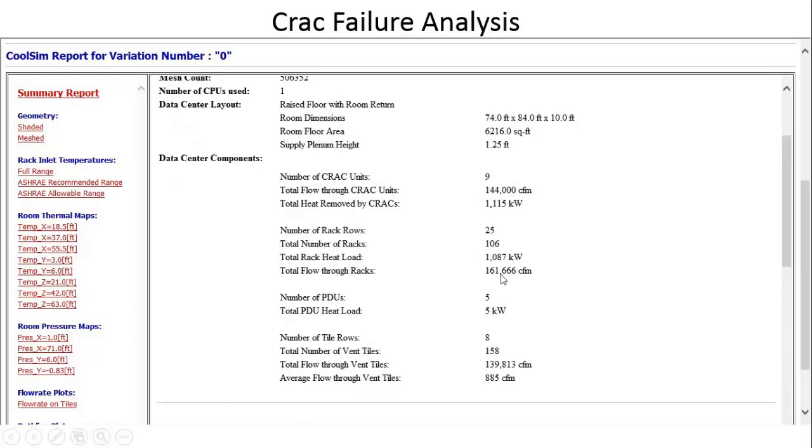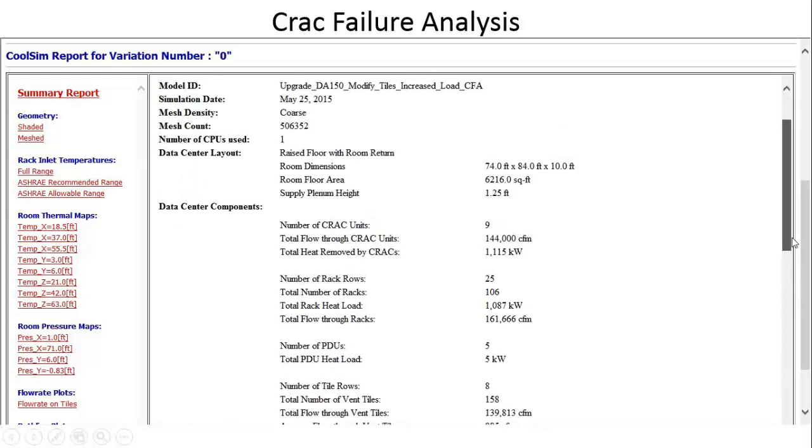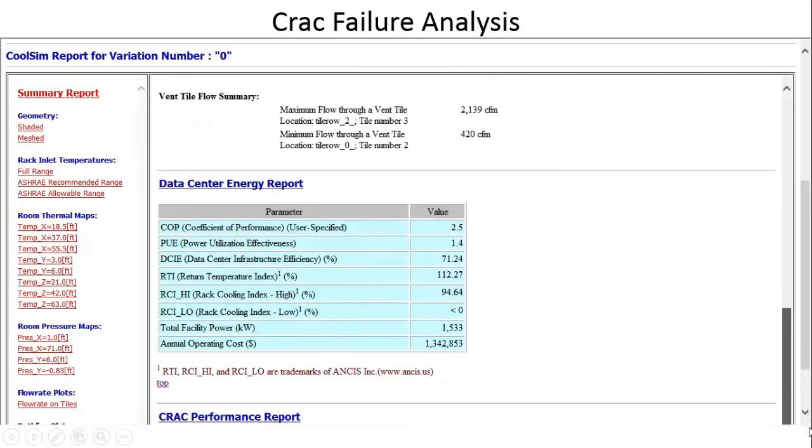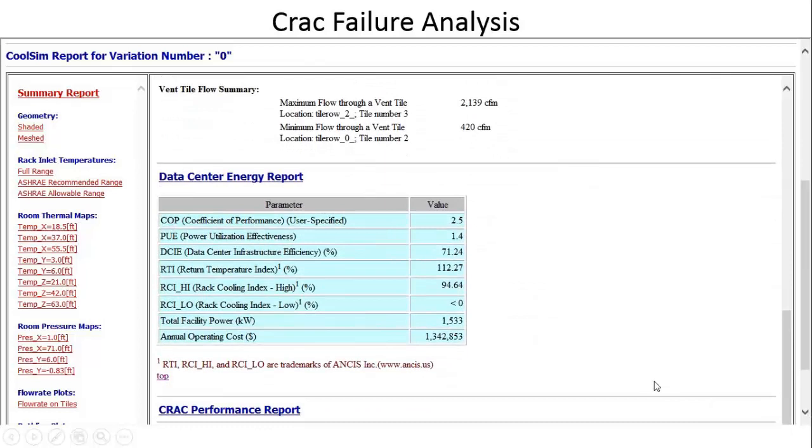I mean, the thing about modeling is you have to assume something, right? So I'm taking a worst case view of it and saying everything is operating at 20 degree delta, which is in fact not always the case, right? Absolutely not, and everything doesn't operate all at the same time. Right. Another point here, well made, is that it doesn't all operate at the same time, and this data center is not going to be completely full right away either. It's going to have some time to come up the curve of load. So we're looking here at worst case conditions.